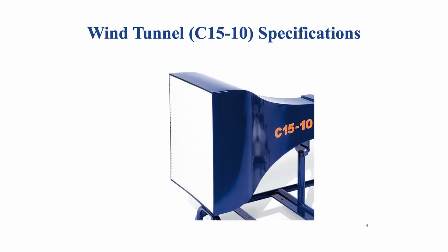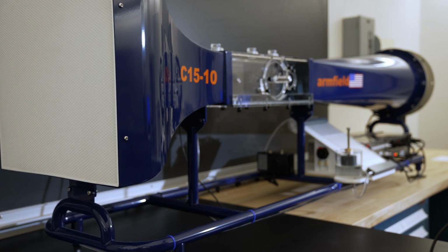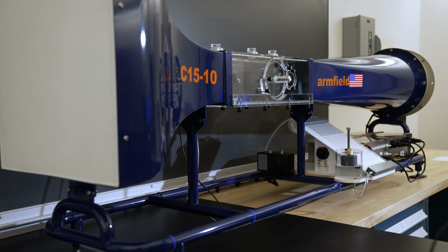The main components of this wind tunnel are a 50 centimeter square inlet that contains a flow straightener in order to smooth the flow and induce fully developed conditions within the test region. The inlet transitions into the test region through a size reduction with a contraction ratio of 9 to 4 to 1.